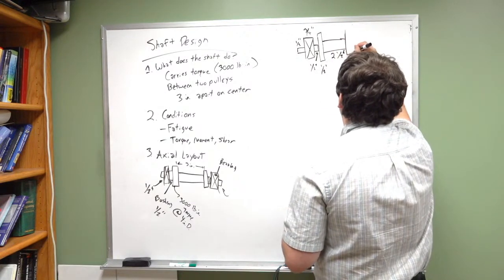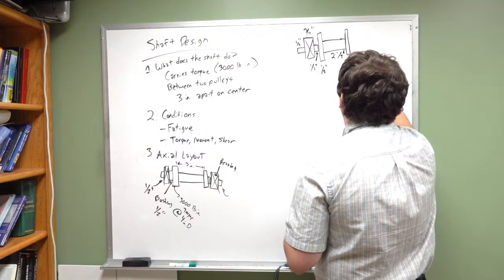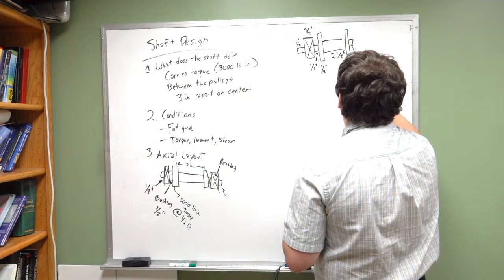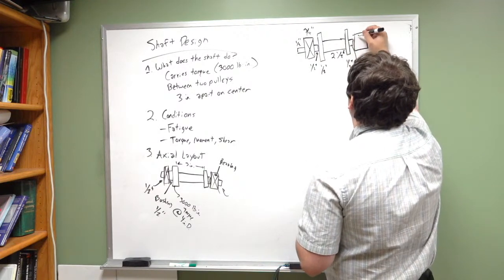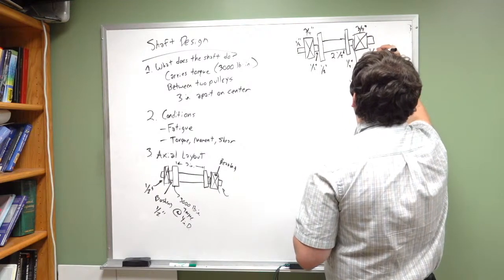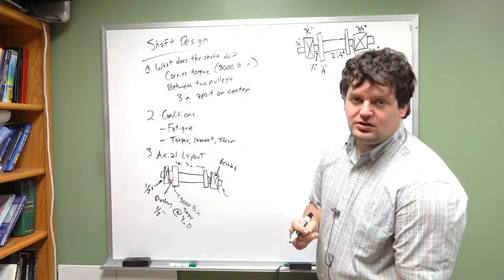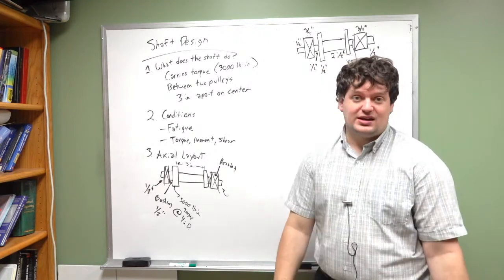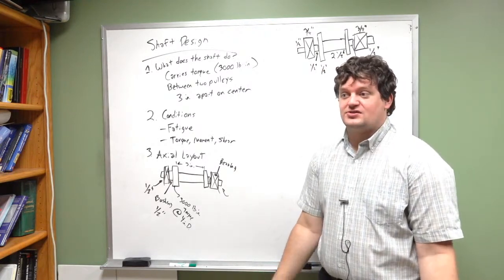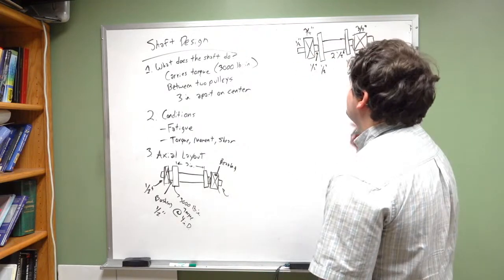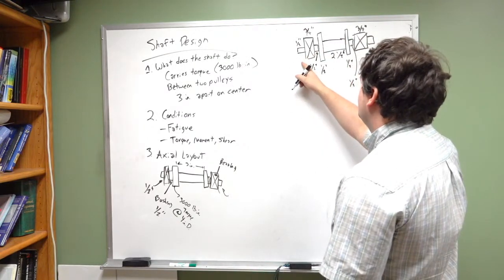Then we've got another pulley over here. It's also 1/2 inch. We've got a bushing, also 1/2 inch. We've got our bearing. The bearing is 3/4 inch, and then we've got 1/2 inch of shaft outside of that. Okay, so I haven't done any real math yet. I'm just looking at components and saying here's how wide they are. From this, I am designing an axle that's